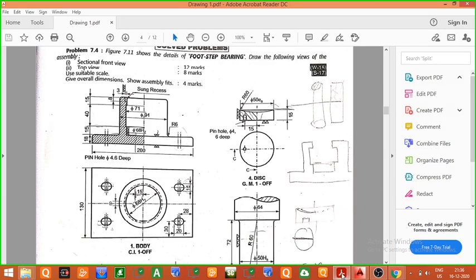Now in the next step, we have to draw this horizontal line, this line as well as this line, both on the left hand side and right hand side. For drawing this horizontal line, first we will identify the dimension. You can see the total distance from this point to this point is 200, whereas the distance from here to here is equal to 94. So if we find the difference of both these dimensions, we get 200 minus 94, that will be equal to 106. So the difference of this length 200 and this diameter 94 is equal to 106 mm.